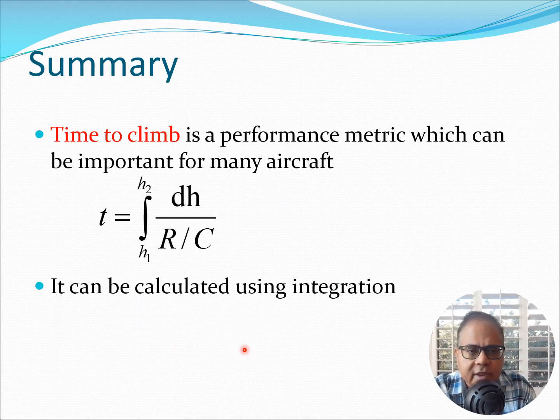To summarize this lecture, we have now extended the concept of rate of climb to time to climb. This is an important performance metric because in case of many aircraft, it's important to know how much time it's going to take to climb from sea level to a given height. You don't want to hang around too long in the low altitude regions because there are a lot of planes which fly there, and also certain altitudes are reserved for certain types of aircraft.